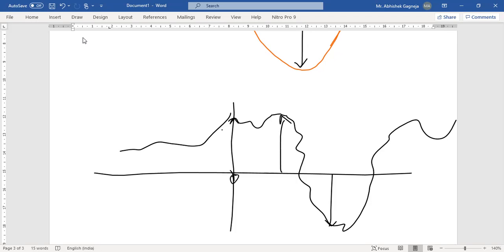At time t equal to 0, when I sample, I'm not going to use the whole data. I'm going to sample this data. So when I sample this data, I'm going to get the information at this point only. And this point's contribution was only from its wave that was meant to be there, and that was PT. Similarly, at this point, the data that I'm going to get is only what was contributed by the wave that existed here. Similarly, at this point, it is going to be only for this one.